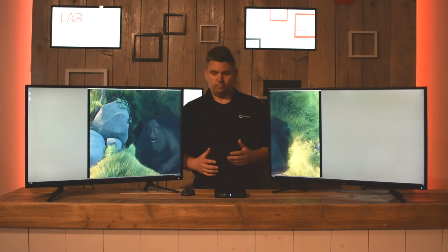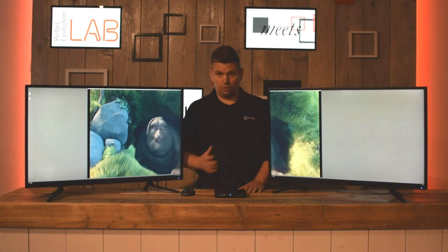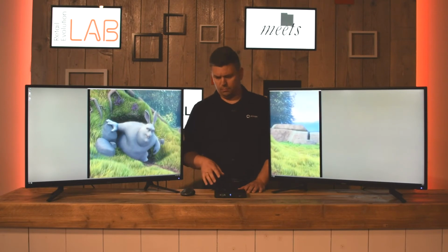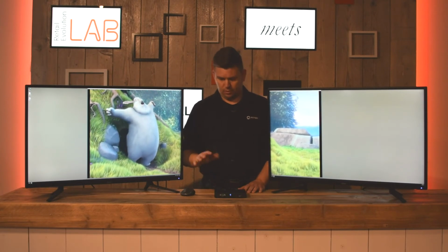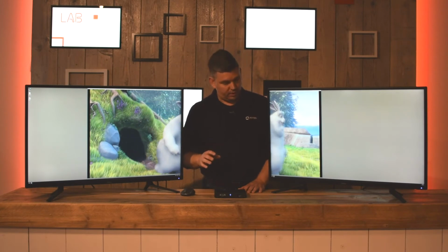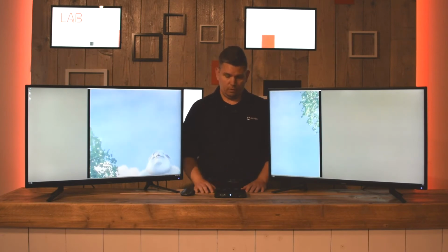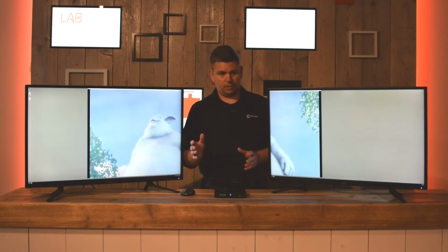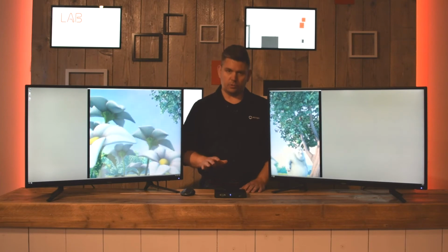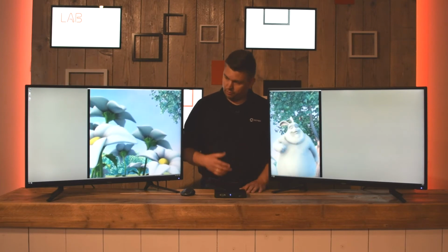Suppose you have dodgy cables or long cables in your setup. Mostly longer than 5 meters is tricky. The EDID data can get lost somehow. So the signal is still there, just the EDID data is no longer available. Then Windows will start complaining and do funny stuff like we saw before.